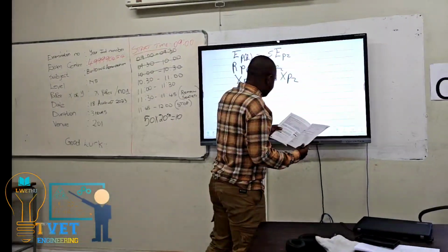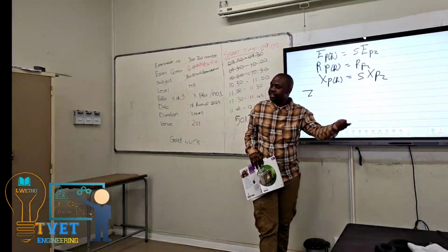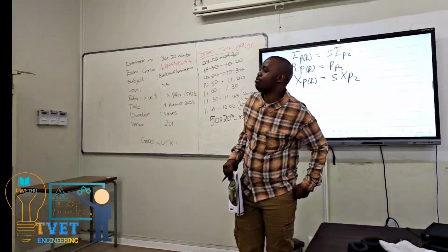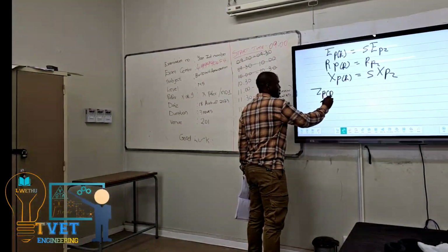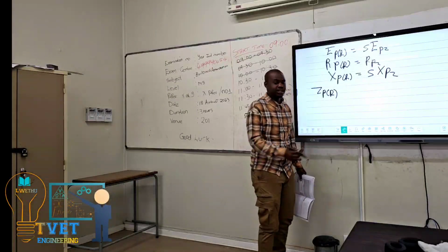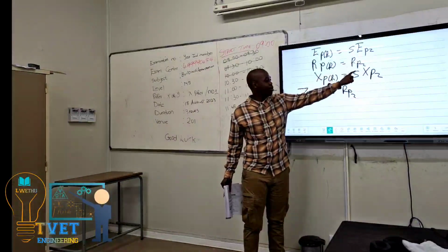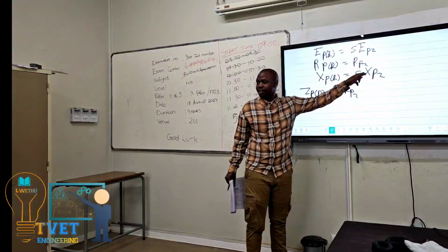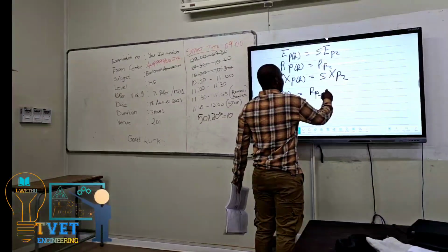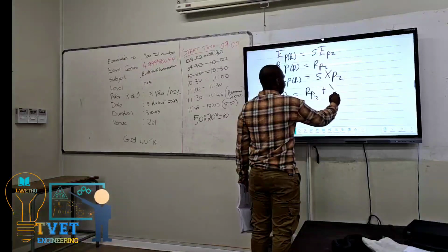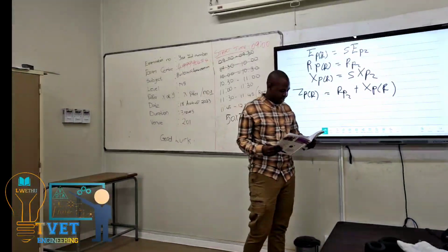Because the reactance is frequency dependent, the impedance must also have a rotating value, which is Z2r equals the square root of R2 squared plus (s X2) squared. Remember, the resistance stays the same and the reactance is the one that changes.